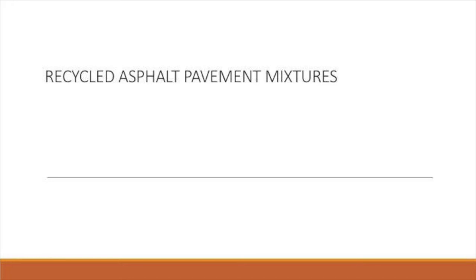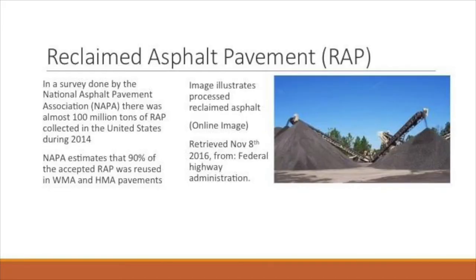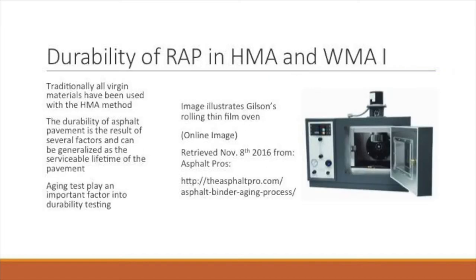recycling systems present today. The benefits of using reclaimed asphalt pavements, or RAP, are lower costs of building materials, reduced amount of virgin materials, and a renewable source of aggregates. The majority of RAP is used for pre-existing binder content. A typical asphalt mix with an RAP content will have a weight percent of RAP replace a portion of the aggregate and binder content. Reused asphalt binders have several effects on the performance of the pavements.